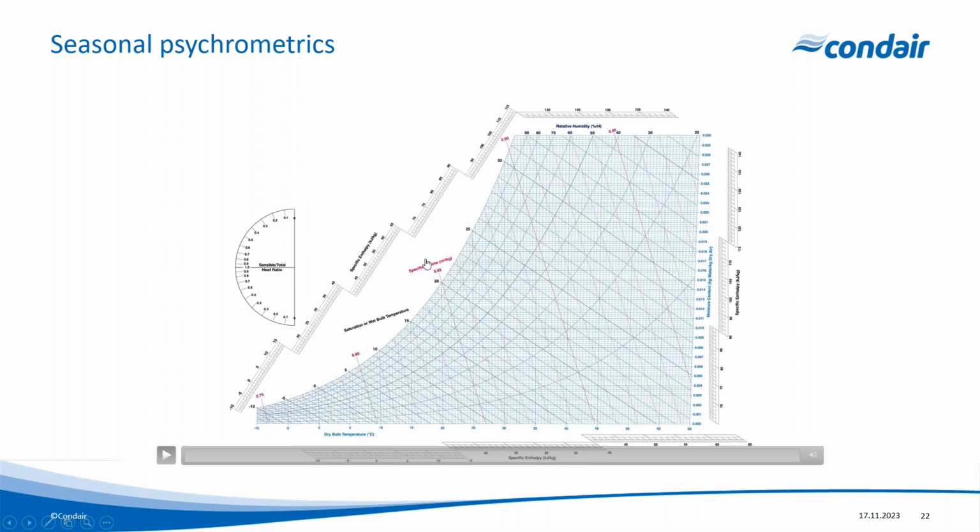And then the final bit of the chart is the specific enthalpy, which is running all the way around the chart. We read this by simply taking our condition, 20 degrees C dry bulb, 50% RH, and drawing a line from this scale intersecting our condition, and then down to the bottom scale, and where the value of the bottom and the top scale is the same, will tell me how much energy is in air at that condition.